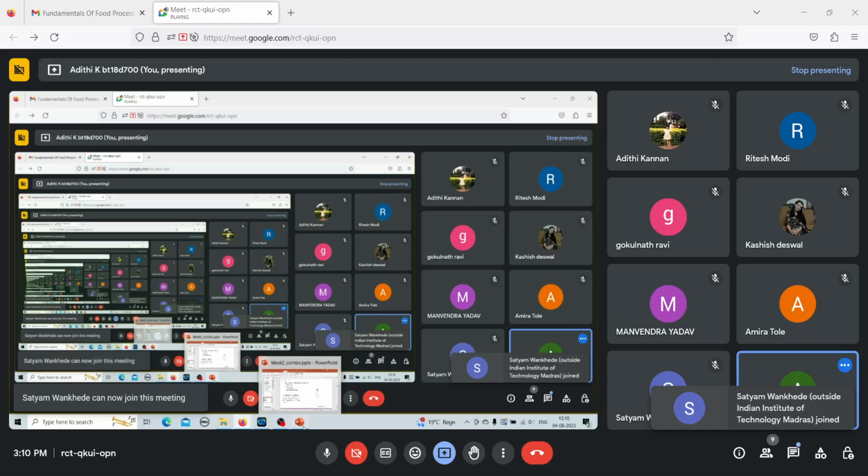The spring represents the elastic nature of the fluid and follows Hooke's law, which is also the case of an elastic solid. The dashpot represents the viscous nature of the fluid and follows Newton's law of viscosity. The dashpot is basically a cylinder with a piston in it, filled with a fluid of viscosity eta. And this spring will have a Young's modulus of E, capital E.